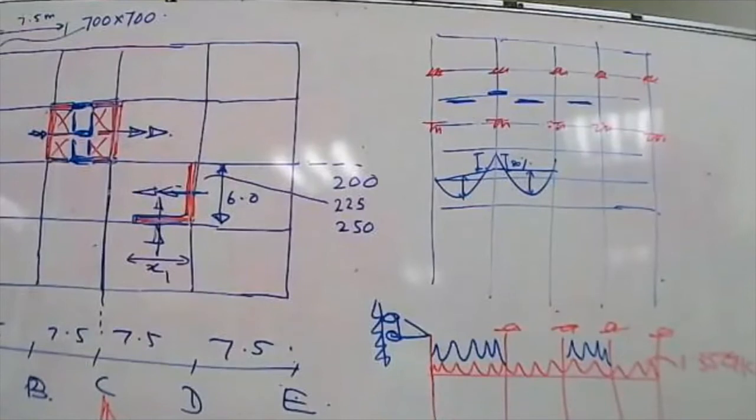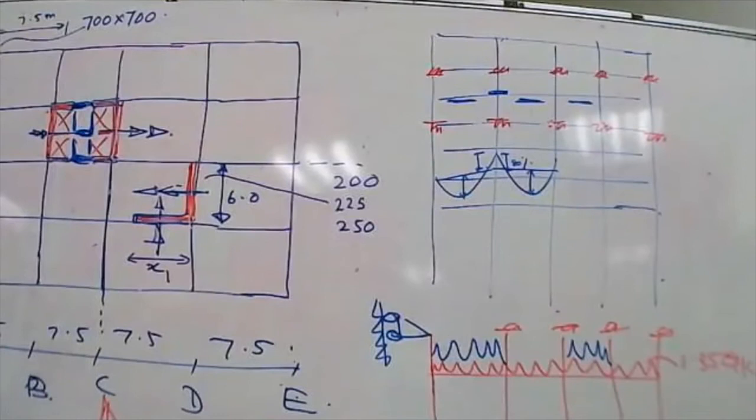Yes, sir. Yes, Professor. So this is not a normal design; this is a design where you like to assess the risk and take some extra precautions that are not given in the code. That extra precaution is that you will over-design the span section slightly, whereas you will do moment redistribution to a reasonable level over the support.